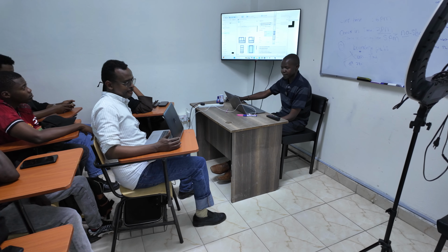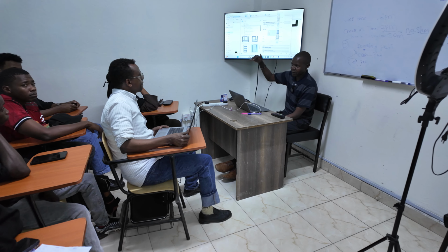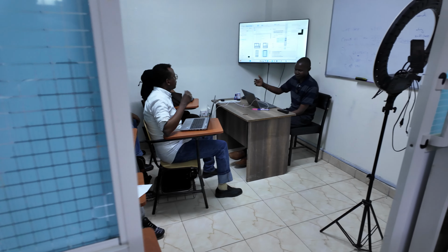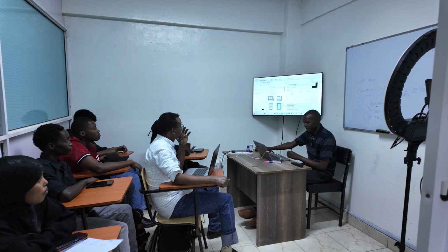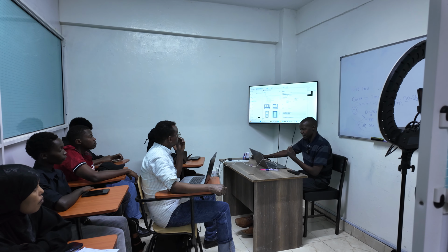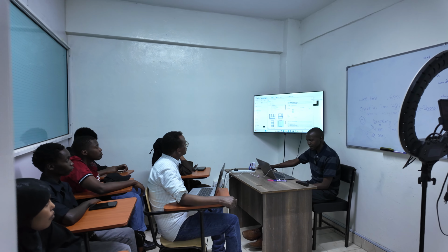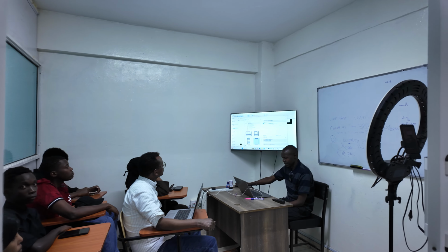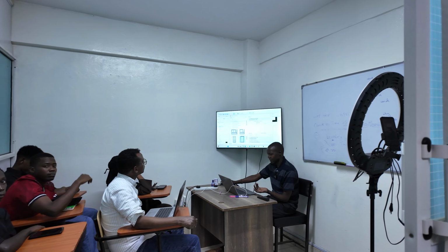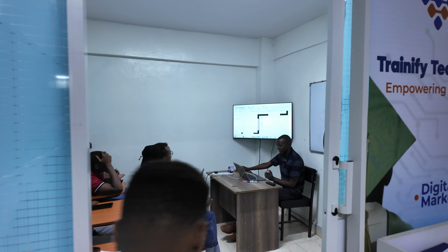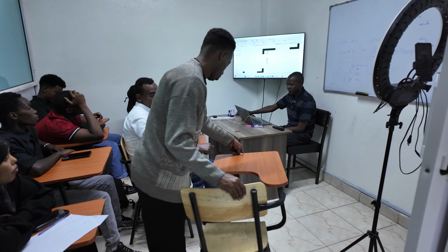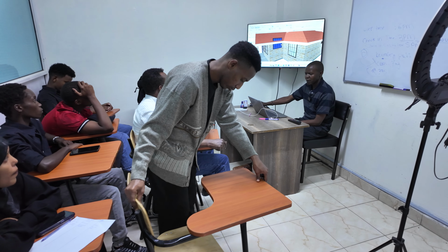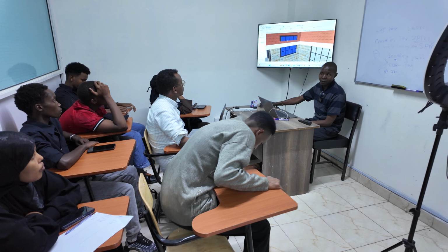like the grids. You see, you have to partition your window. For example, if you want it one glass, fine, there's no grid. But if you want a grid, it will be fine. For example, let me do that. And then you have 4 for the vertical and horizontal. Then everything remains the same. So whatever you change is there. When I click, and then come and place this window here. So when I come to my 3D, already you can see the window is blue.